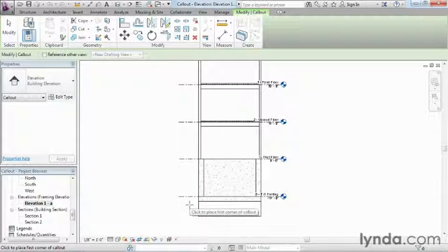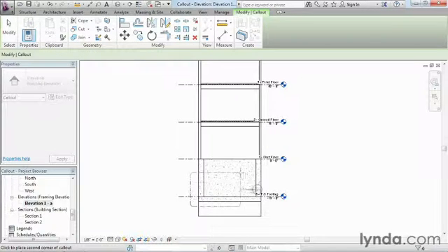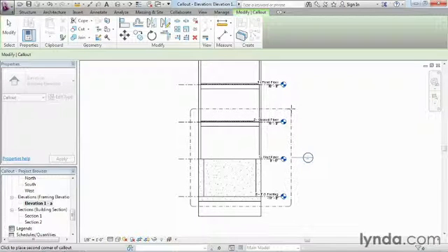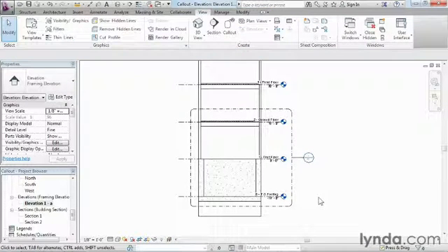Next, I need to draw that little bubble I keep mentioning again and again. And that's by selecting here and holding the mouse button down and then pulling up and just creating this big bubble or window around this view. Now, this is fairly standard structural or architectural annotation, so there's a good chance you might recognize it. But really, all you have to do is just click here, and it'll automatically draw a window with that bubble associated around that particular area.